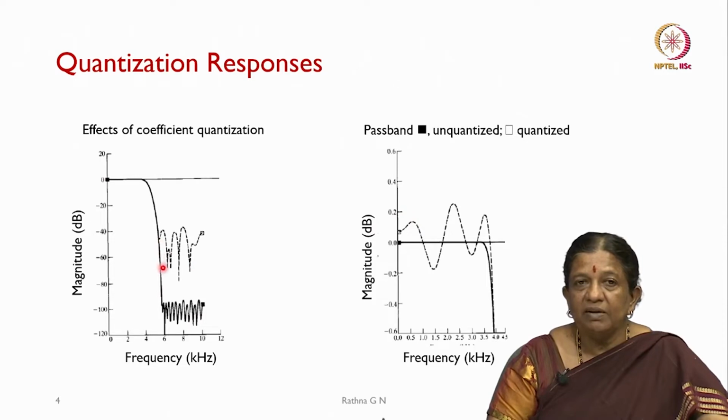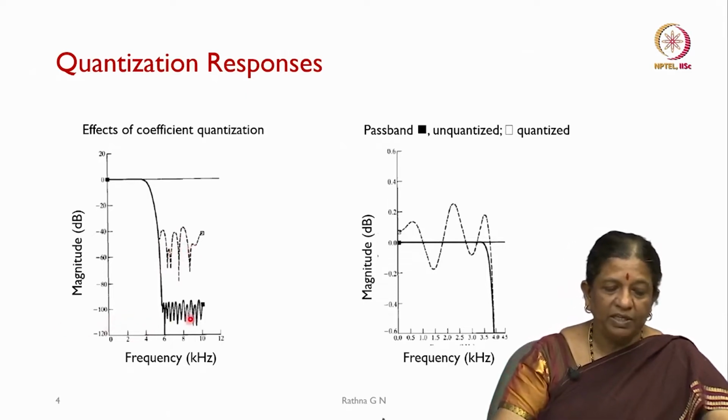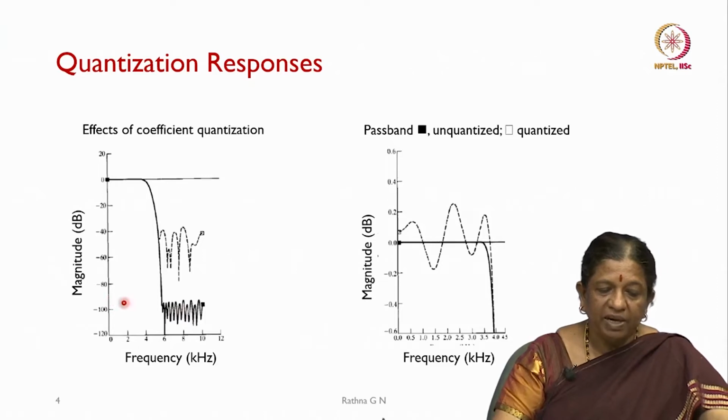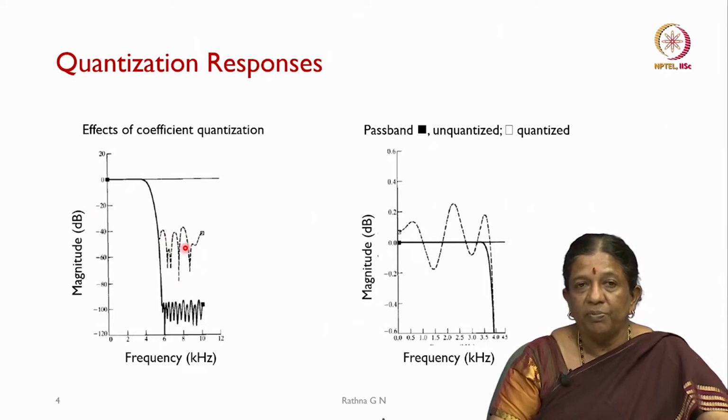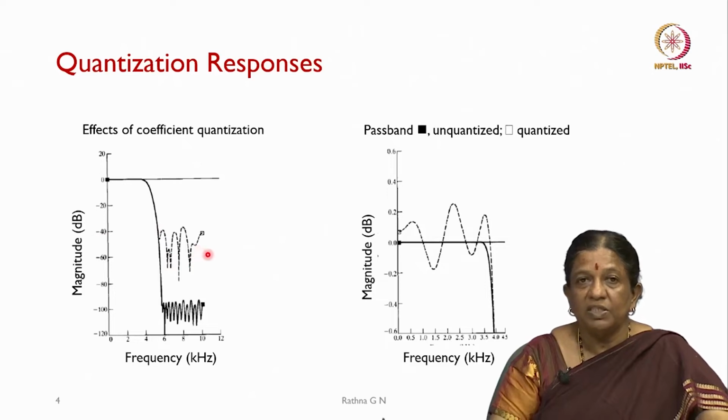You will see that my cutoff frequency or stop band just gets moved up, from greater than minus 80 dB, which will drop down to around minus 30 to 40 dB. So, this is the coefficient quantization. One has to consider this when we are using hardware, so our design has to account for these quantization effects.